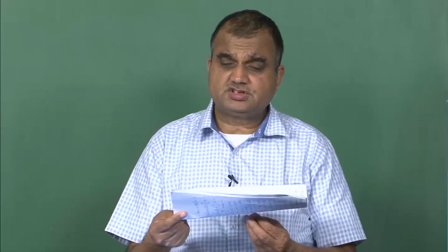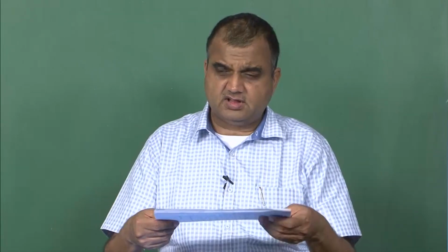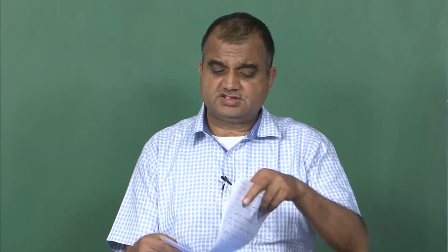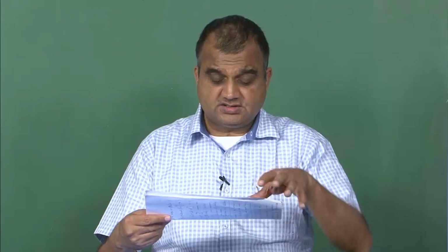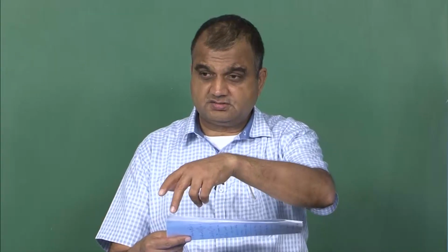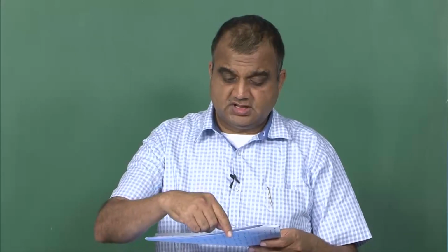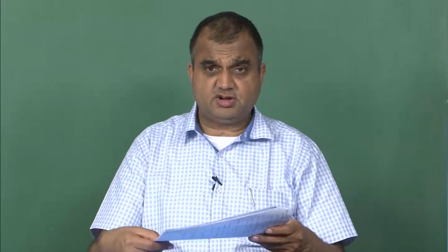What kind of disturbance can I make? How can I disturb this? I can disturb it in any way. I can disturb it like this, whatever shape, does not matter, any shape, as long as I do not violate the kinematic boundary conditions, okay. So, any function which does not violate the kinematic boundary conditions. So, in this case, what are the kinematic boundary conditions?